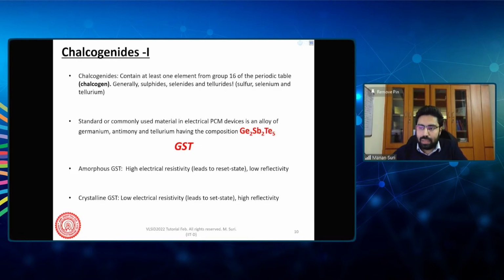In fact, there are many materials in which you can induce phase changes, but if those phase changes are not stable, if they are not energy efficient, and if it is not ensured that they would stay in that state under certain operating or environmental conditions, it would not become industry grade non-volatile memory. So most of the material engineering goes to ensure that after the phase change, the phases are reliable and stable, so that your zeros and ones that you're storing inside the technology remain safe.